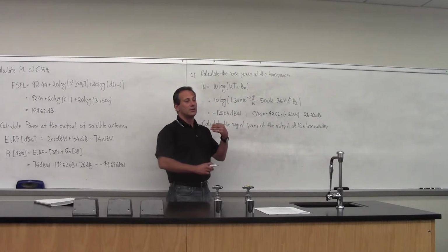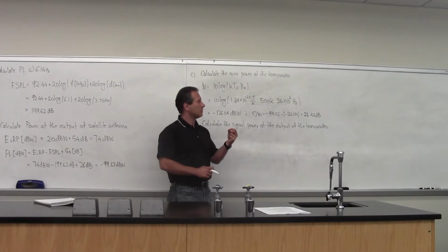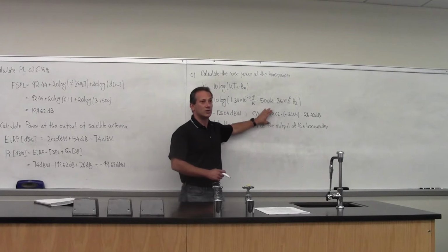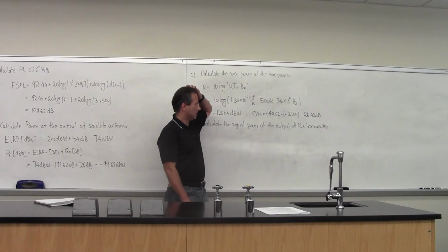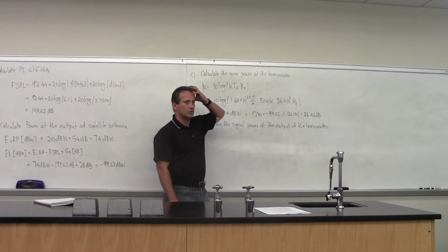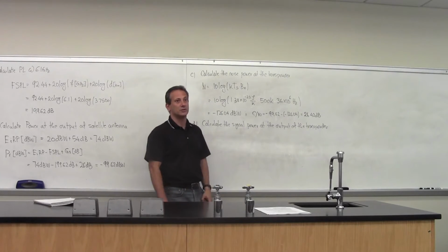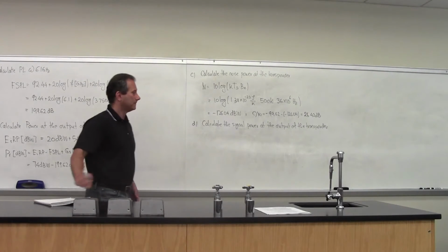The tricky part here is to look at what matters, and this is signal to noise or carrier to noise ratio. It's not the raw power, because you can have a signal of high power but very poor signal to noise ratio.